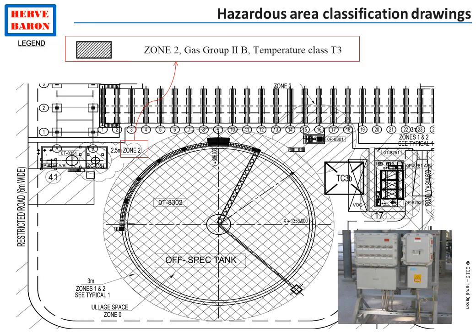Safety consolidates the hazardous areas around all equipment and lines and draws the same in the hazardous area classification drawings. It then specifies that electrical and instrumentation equipment within a hazardous area must have an explosion protection so that there cannot be an ignition source for the potential flammable atmosphere that could develop in the area.